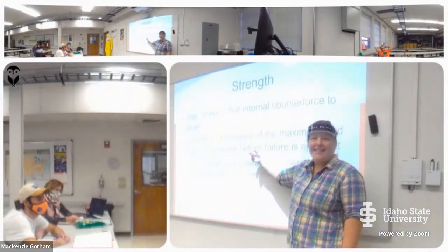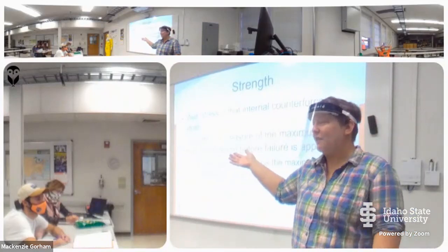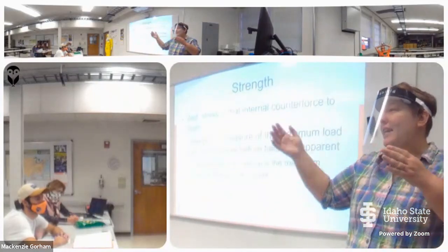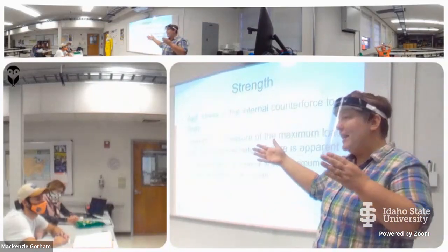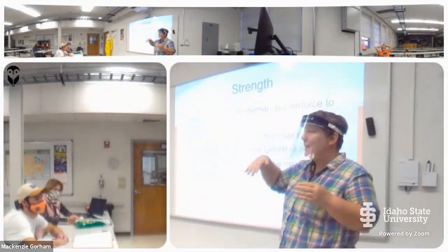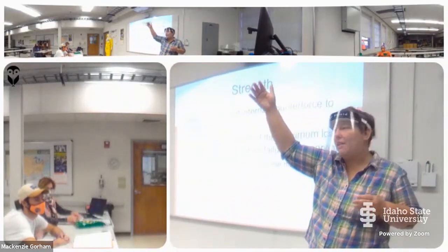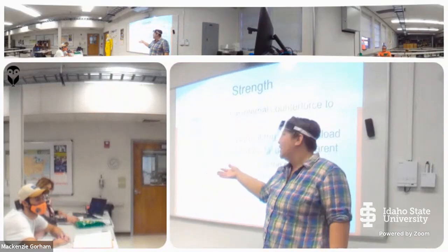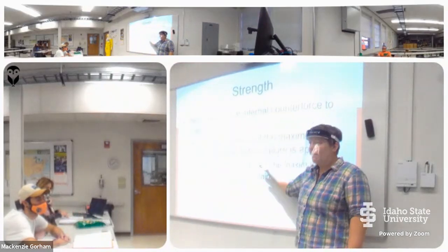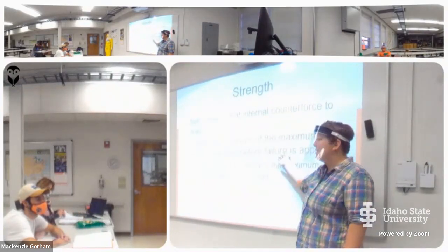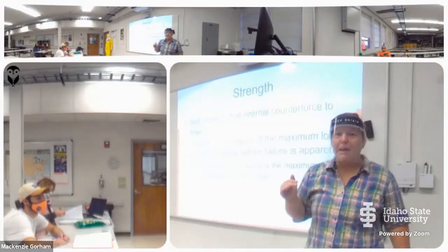At the yield point, that elastic deformation starts yielding the plastic deformation, and we start to see permanent damage to the metal, right? And then we get all the way to maximum tensile strength, and from there, we fracture. And that's a definite failure, right? So we start to see this after our elastic deformation.